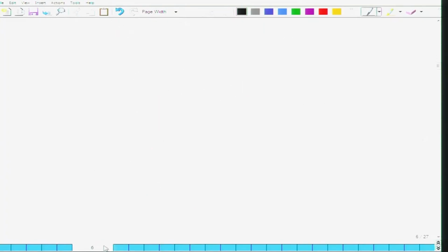But what is omega L by beta? I can simplify this further because I know the relationship between omega and beta, right. So, I have omega by beta into L, but omega by beta is nothing but the phase velocity up into L. up, the phase velocity, is simply given by 1 by square root of LC for this particular lossless transmission line. Multiplying this one by L will give you square root of L by C.